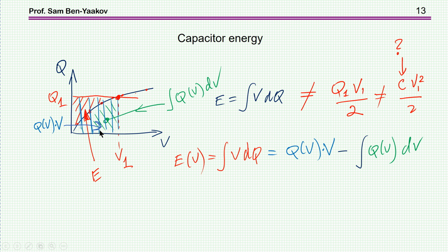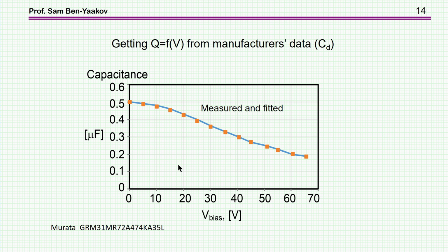You can get it very easily with simulation. So let me just demonstrate how to get all these parameters by simulation. We start off with this local capacitance as a function of voltage. This chart, by the way, is a result of measurements that we have actually made on this particular capacitor we are talking about. And then we digitize it to get this array.